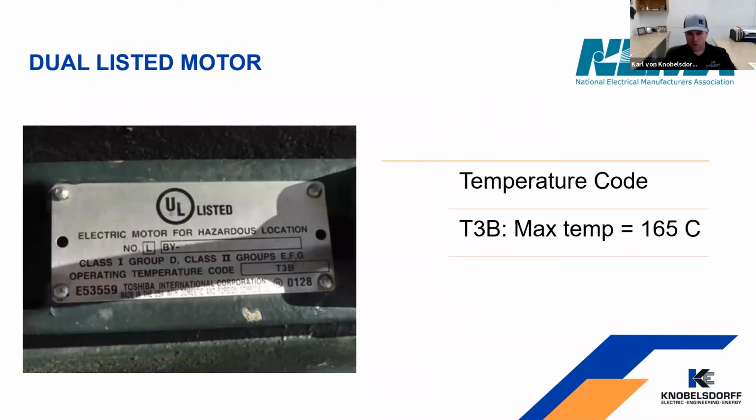Now here's a motor picture, which kind of goes back to that question that was asked by somebody here a little bit earlier. So this is another tag that you'll see on a motor that's rated for a hazardous location. So this motor you'll see has a Class 1 Group D or Class 2 Groups E, F, and G. And it's got an operating temperature code of T3B.